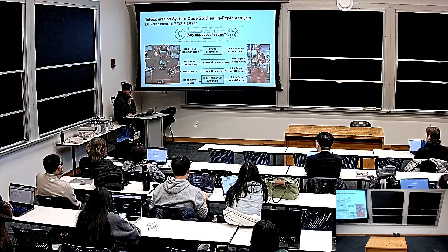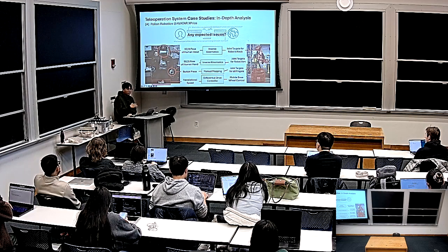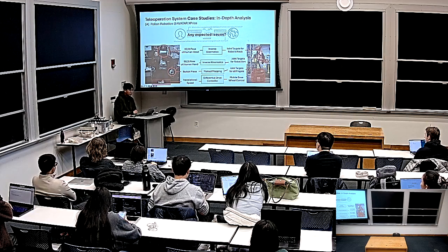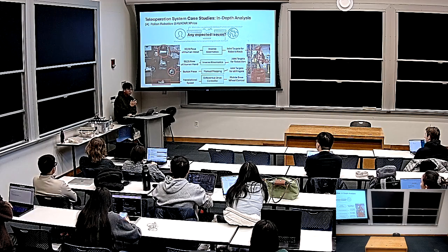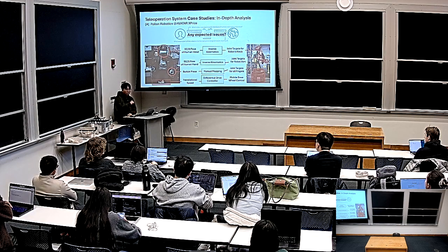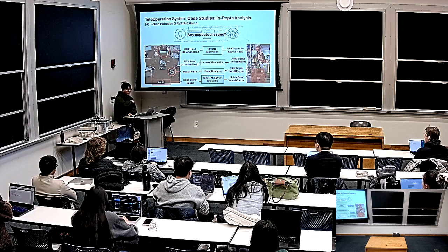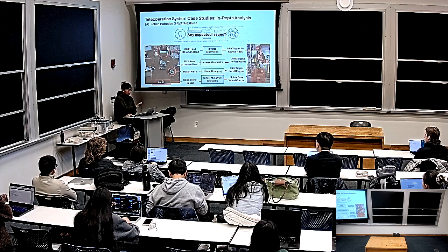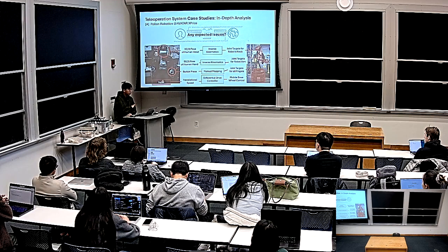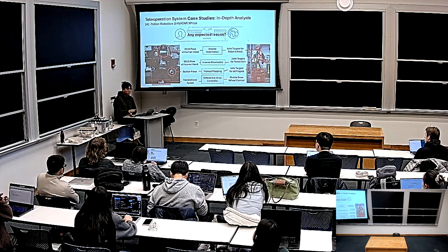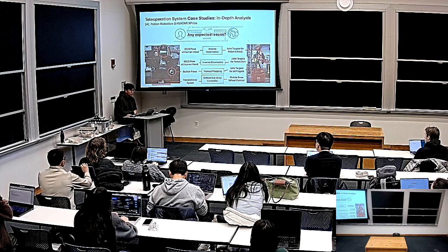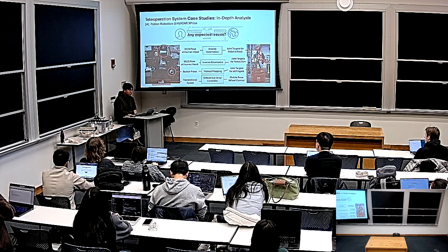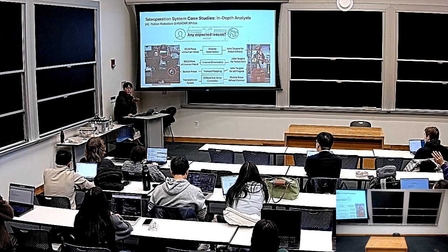But even if the target SE3 pose is within the robot's workspace, there might still be some issues. There's a thing called singularities of robot arms. If you have taken a robot manipulation class or any robotics 101 class, there are singularities of robot arms where the robot behaves very weirdly in certain configurations, because the inverse kinematics has to choose one solution among infinitely many solutions, so it kind of freaks out. So relying on inverse kinematics can cause certain issues, but there are clever ways to avoid it. Yeah, question.